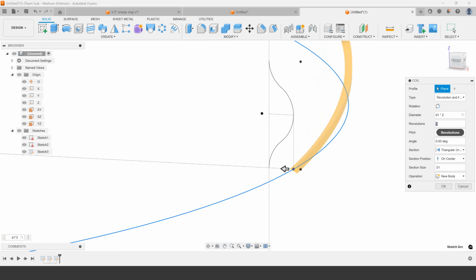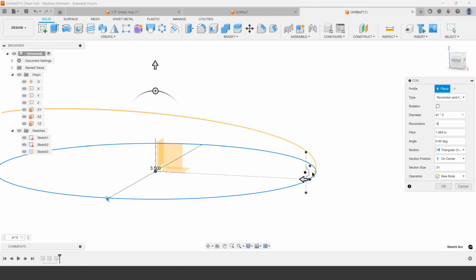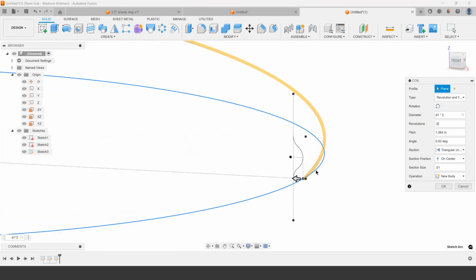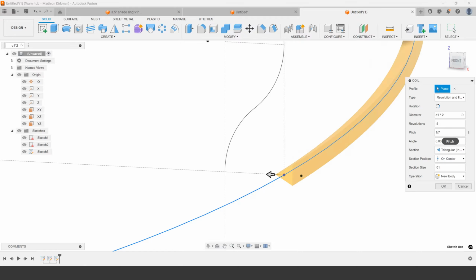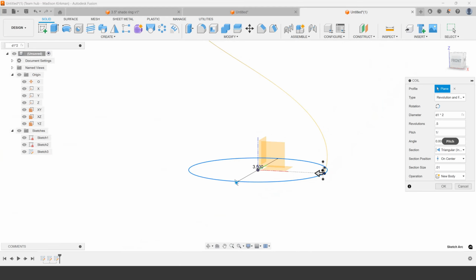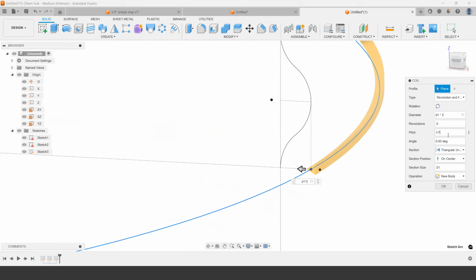So I produce that. Now you have to produce 1/2 of the thread. This is assuming that this is a single lead thread and there's not 3 threads at 120-degree phasing or something of the like. I'm sure if you're smart enough to handle multi-lead thread, you can figure out how to manipulate the numbers to do something else. But for simple single lead thread, I'm going to do 1/2 rotation, pitch. Again, I said earlier this is 1/7 of an inch; there's 1/7 for every rotation. 1/7 of an inch is the progression.